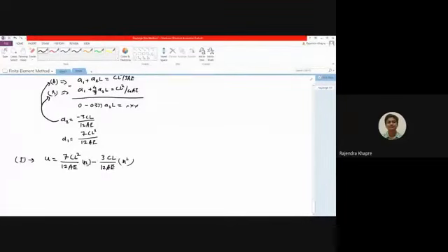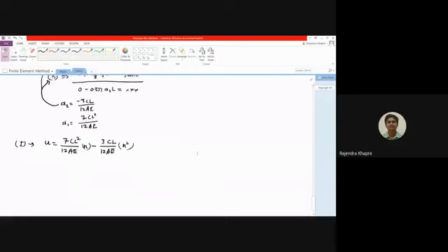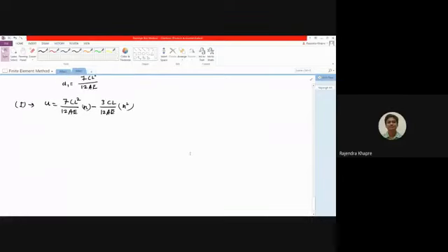So now this is the final value of the unknown displacement. Now let us plot the variation of displacement with the help of the equation which we have obtained. For this purpose let me draw a simple line over here. Here X equals 0 and here X equals L. Now in this expression, if you substitute X as 0, everything is going to become 0. So the displacement at this point will be 0.